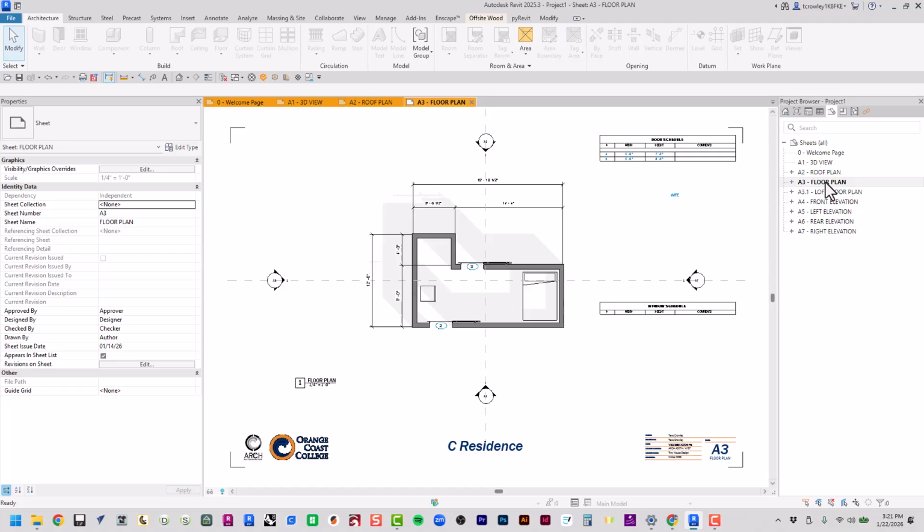right over there where the door is, there'd just be an air gap, right? There's a side light next to it, so I would see this little pane of glass and the structure on the left and right side of it. I would see the portions of the wall that create the rough opening, and same thing with the other doors and the other side lights in this room. But I would not perceive anything above that 4-foot cut plane, right? I'm simply cutting at 4 feet and looking straight down. That's what a plan or floor plan is.